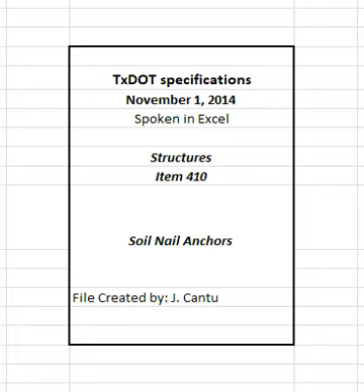Provide gauges that extend and retract freely and move smoothly throughout their range. Provide a rigid and secure system to support the gauge independently of the jack or reaction system. Verification test nail acceptance criteria.